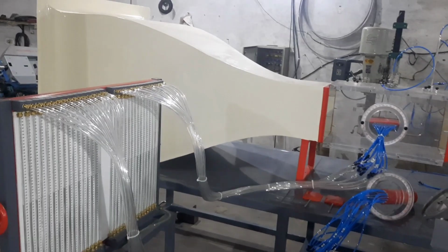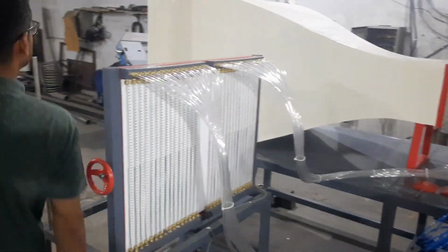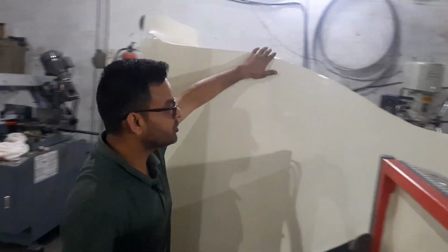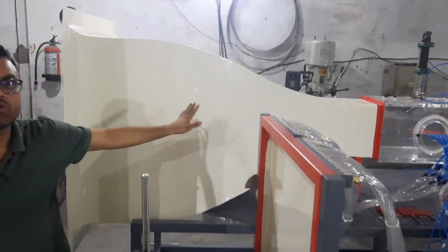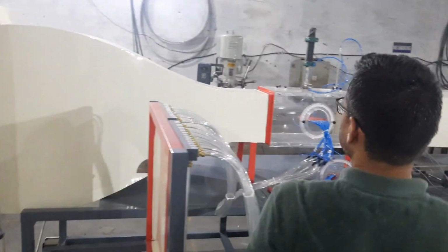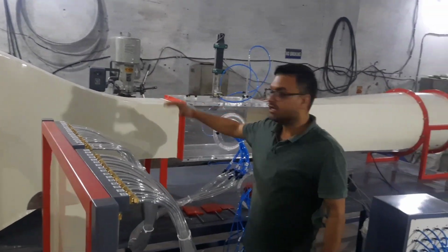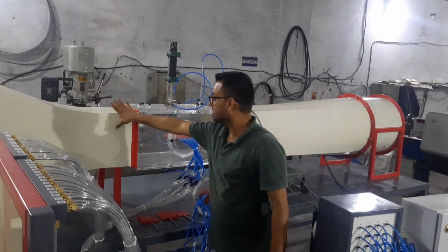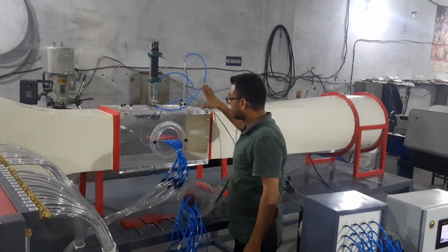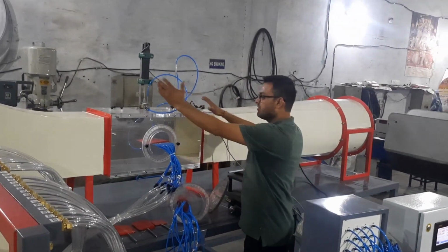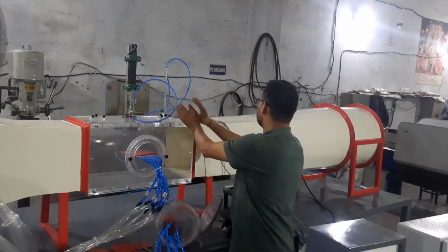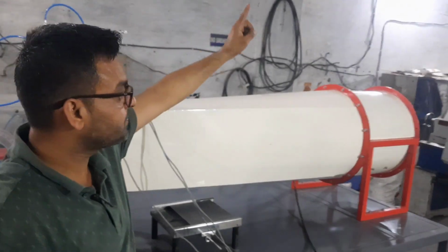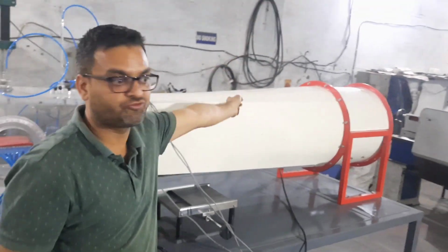As you can see, this wind tunnel starts with an effuser. The air from that effuser enters a nozzle, also known as the contraction cone, which is used to accelerate the velocity in a linear proportion. Then the accelerated air passes into this test section, or we can say the transparent test section, the working section. From the working section, the air passes through this diffuser cone, then through a variable speed axial fan, and finally into the atmosphere.